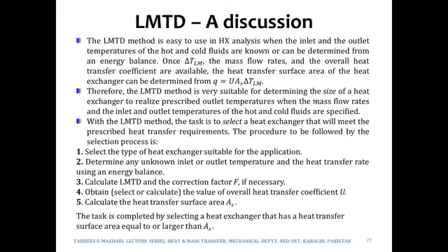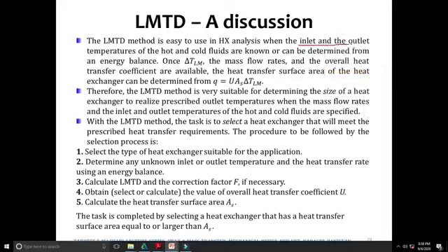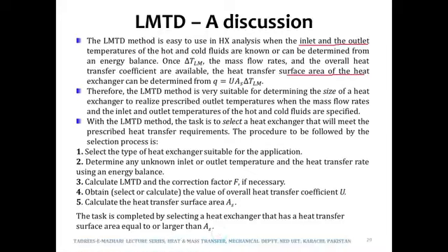So this method will be used when we know the inlet and exit temperatures of both the fluids, and the job is to find out the heat transfer surface area, means the sizing of the heat exchanger, means when we need to select the heat exchanger. So this is when LMTD will be used. Therefore the LMTD method is very suitable for determining the size or the area of a heat exchanger.